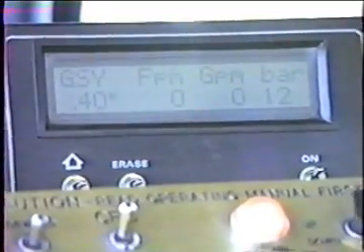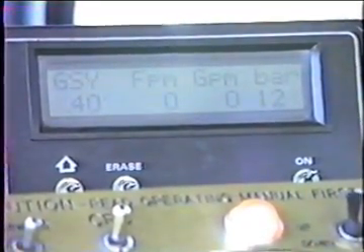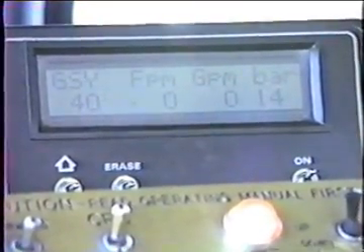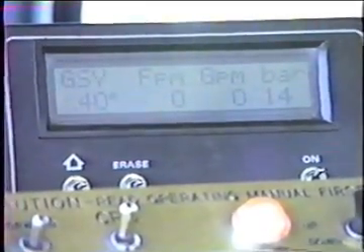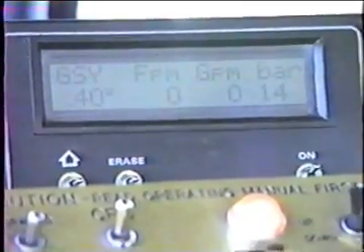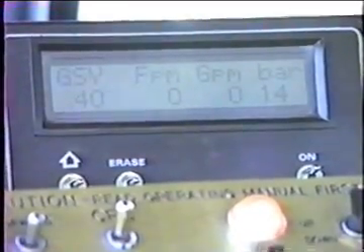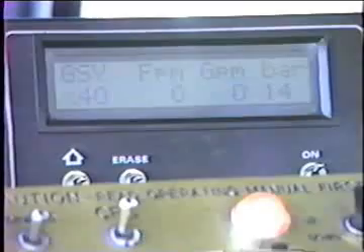Select the bar width. Let's say today we're going to start out shooting 14 feet wide, and we've decided to do it mostly on the left hand side of the truck. There's 14, we're ready to go. We do nothing else as far as setting the spread rate. Now when we take off, when we turn on the master switch, the spray bar will spray.